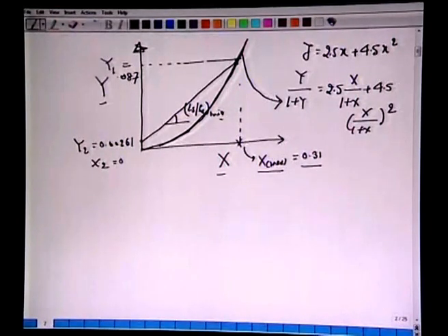Okay. So one can solve graphically, and if you want to solve these numbers analytically, all you have to do is take this operating line equation, intersect and solve it together with this equilibrium curve. You can see right here that solving analytically may be a bit cumbersome because the equation is quadratic. One has to do some iteration here.